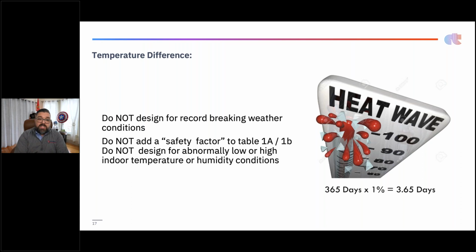That's where Washington's listed. 1B would be like microclimates like Arizona or Miami or Hawaii, right? Where we don't design the same because of really high or really low humidity. But it's really important that we don't just look at the outdoor design conditions, but we also design to the correct indoor design conditions as well. And that's set in the International Energy Conservation Code.